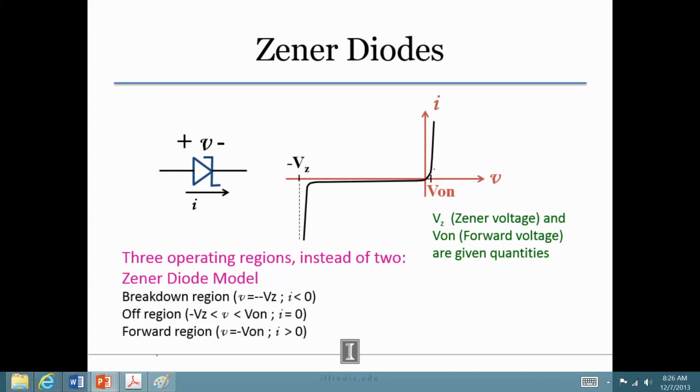Alright, anyhow, a regular diode has this turn on, but the Zener diode also has this breakdown in reverse bias voltage. Okay, actually all diodes have some sort of a breakdown, but Zener breakdown is particularly sharp. It's actually nearly vertical here, or a very nice corner. Okay, and we can also control the Zener voltage by the way we build the diode. And that becomes very useful.